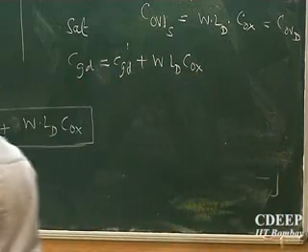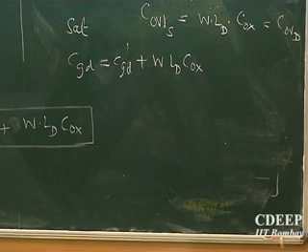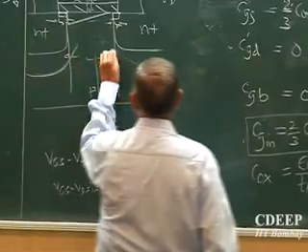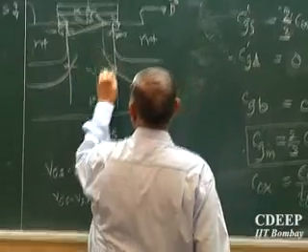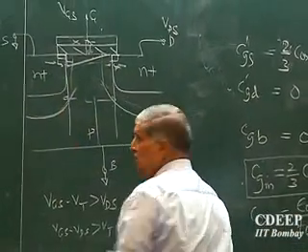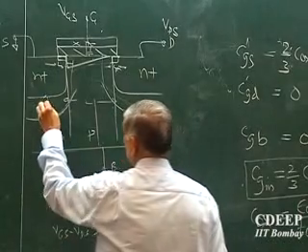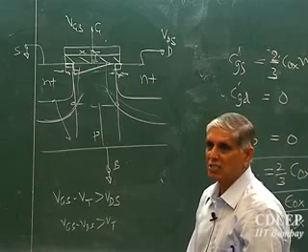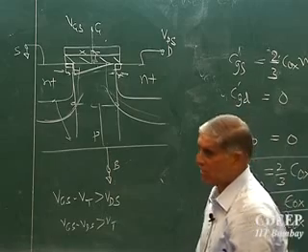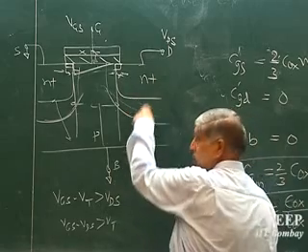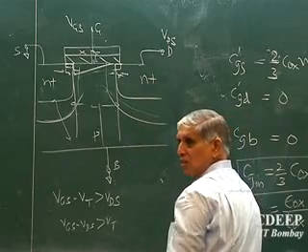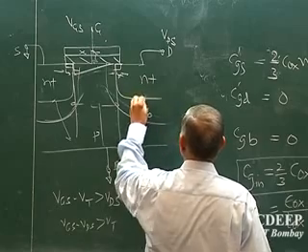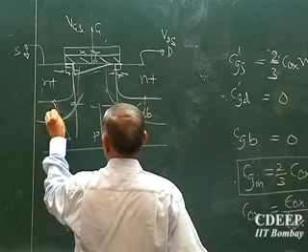So if I now see my transistor once again carefully, there is some more capacitor. There is a depletion layer associated here. What is this? This is a PN junction. Under zero bias, it is also reverse bias. But this side is really heavily reverse bias. So I have two more capacitances. This is called CDB and this is called CSB.